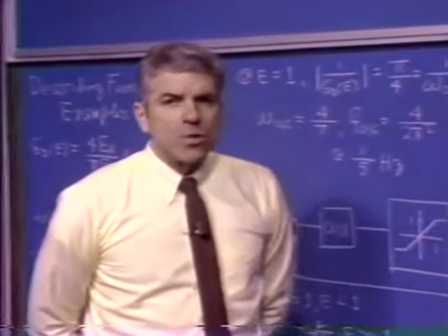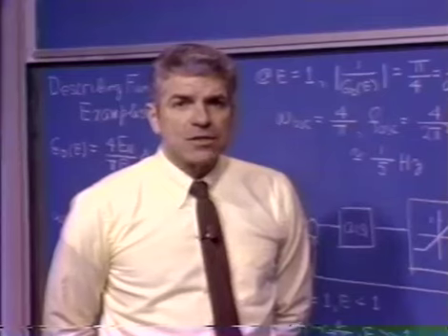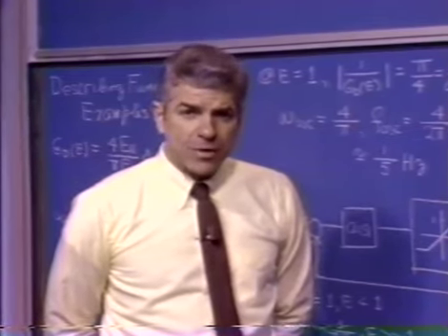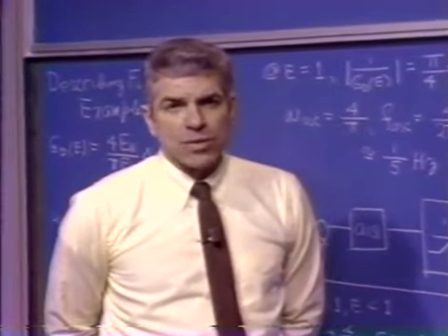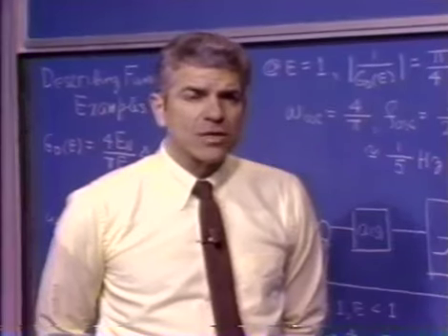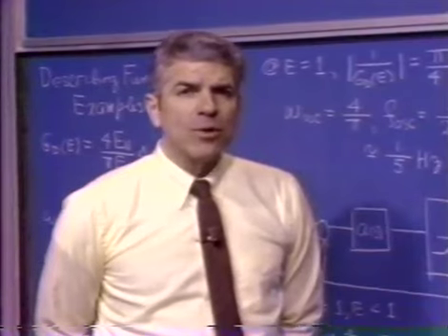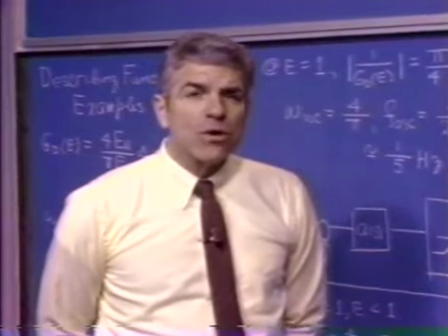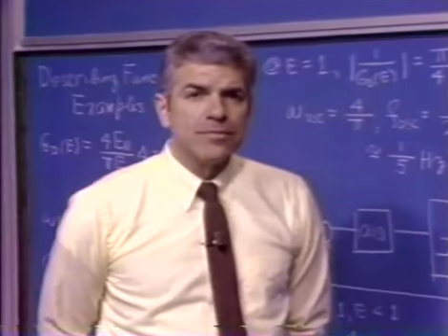There's a question, what does this mean? Does this system oscillate? There's two intersections. If it oscillates, how do we determine the parameters of the oscillation? Which of those intersections controls the oscillation? Which dominates the characteristics of the oscillation? This sort of a system is called a conditionally stable one. And next time we're going to go through the analysis of this sort of a system and illustrate it with an example. Thank you.